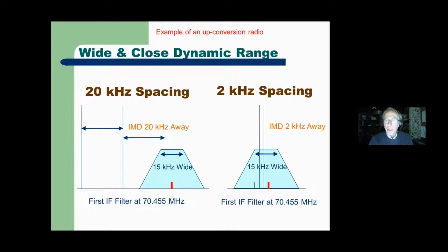So what I did was move the two test signals closer together, and I just picked 2 kilohertz because it was close enough it'd go through really any roofing filter at the time. And suddenly the numbers that were up in the 80s went down into the 50s. So that was what I started doing way back before we had the internet and just had a published chart.